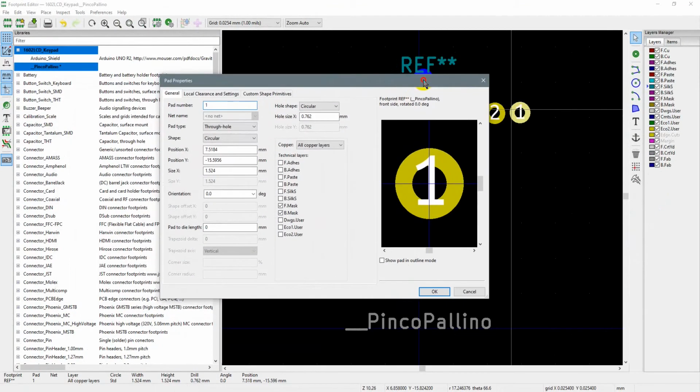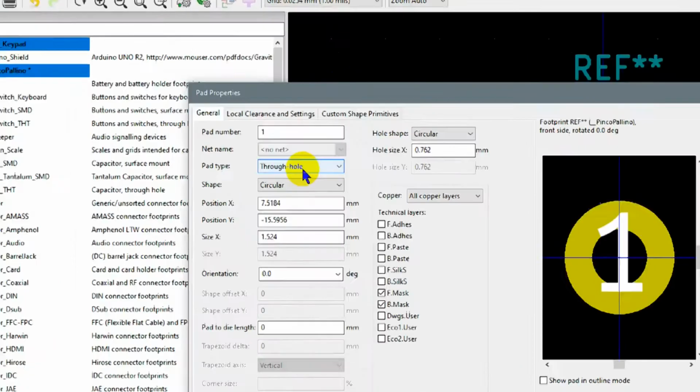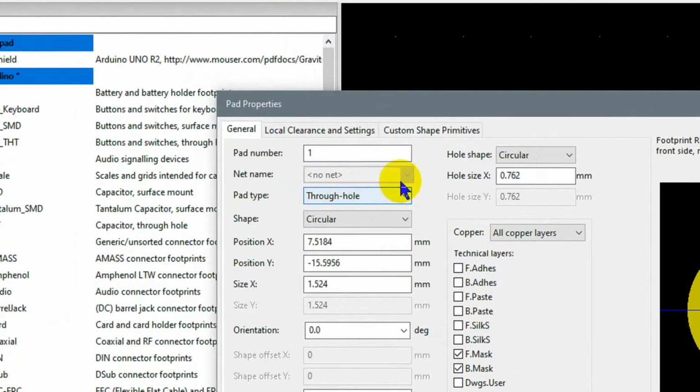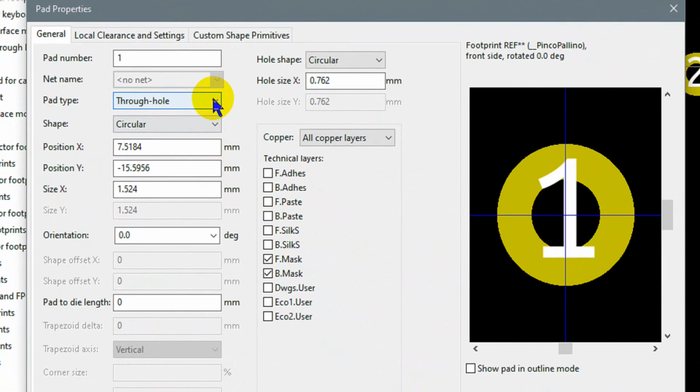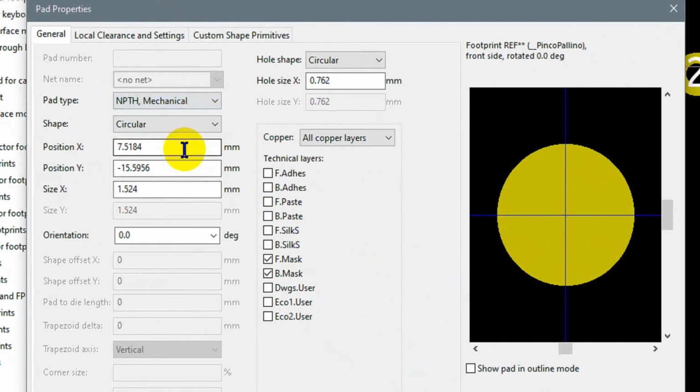Okay, now this one is relative to pad 1, and as you can see here, there is the possibility to give some characteristics of this pad. So the first one is through hole, or SMD, or connector, or mechanical, or anything that can be on a circuit. For the symbol we created before, it must be compliant. In this case, for us, it's a through hole,